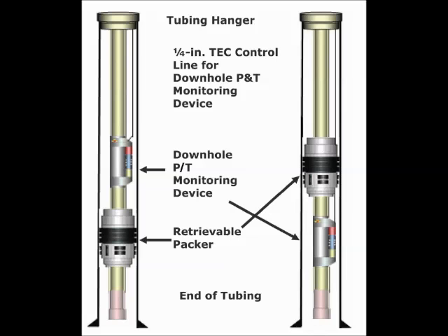Downhole sensors (DHS) are devices installed to monitor, measure and transmit data on fluid flow, fluid properties, and other well performance data. DHS include permanent pressure and temperature gauges, distributed temperature and pressure sensors, sand production sensors, seismic sensors and single, multi-phase flow meters.